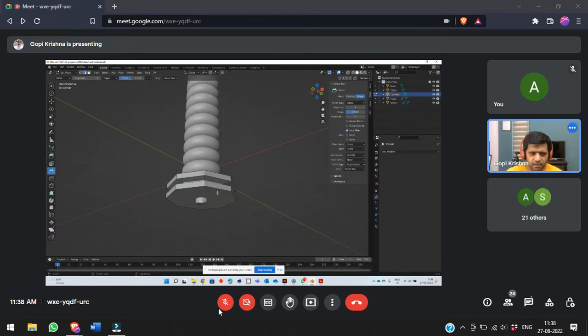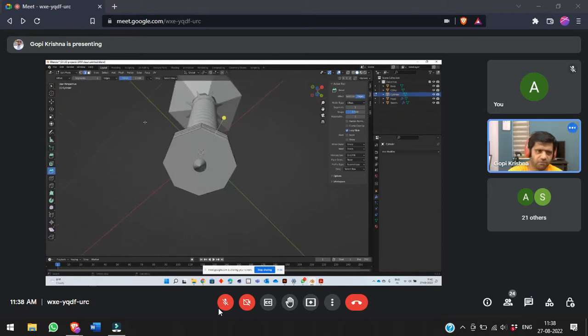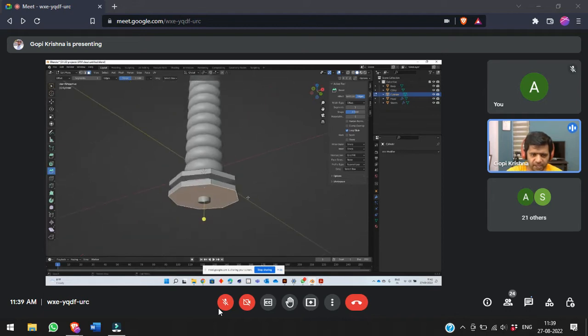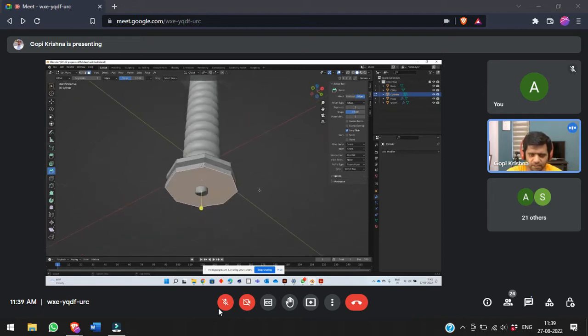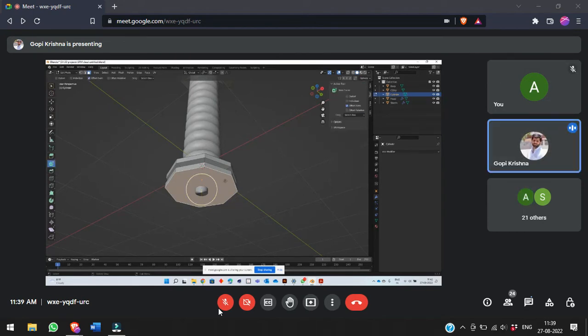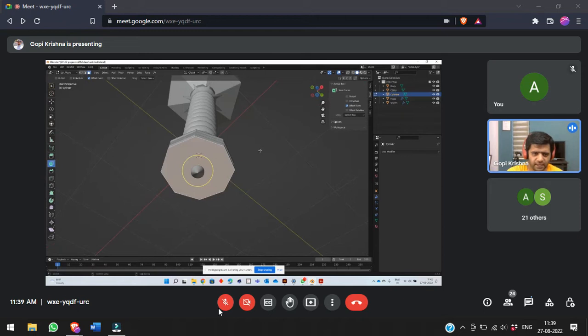Instead, I'll select the bottom face and I need to create one additional face inside. How do you do that? If I want to create a face inside this face, what was the code for that? I, or insert face. Yes. I select insert face and then I create one inside.